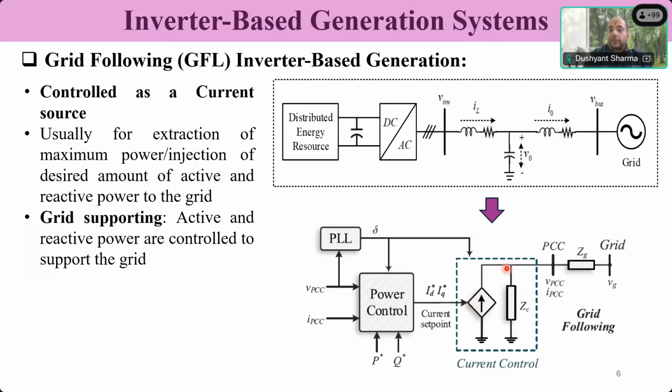So first of all, we have to sense the phase angle of the bus voltage. In terms of phasors, we have a bus voltage phasor, and the current phasor can be in same phase, can lead, can lag. If it is in same phase, it will inject only active power. If it is leading, it will inject reactive power. If it is lagging, it will basically draw reactive power.